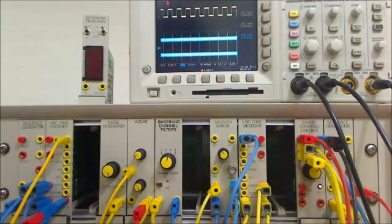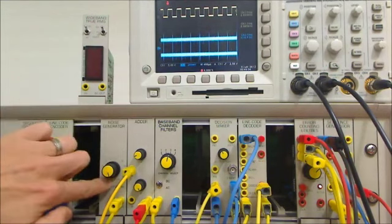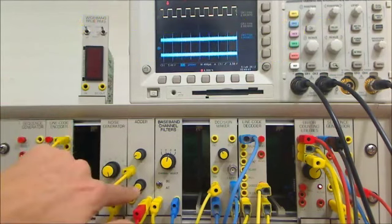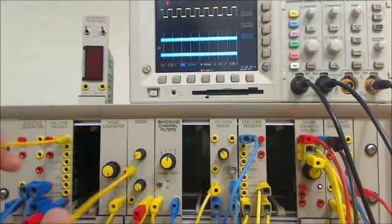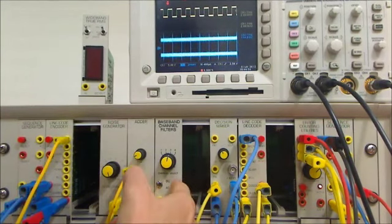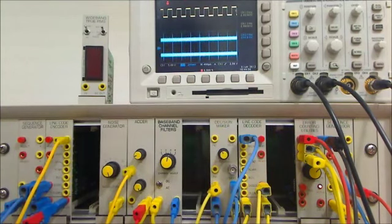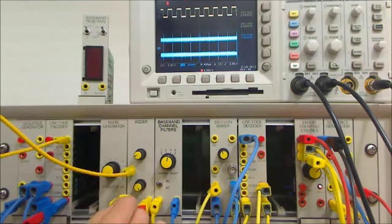I've selected the levels of the gains at the adder in order to get an appropriate signal to noise level. I've set the noise generator to a mid-level of plus 14 dB. The gain at the adder is set to maximum, so we have the maximum level of noise going into the adder, and we have a minimal amount of signal going into the adder. The reason we need a high level of noise coming into the channel is because the baseband channel filter eliminates so much of the power of the noise that there's very little noise power left.